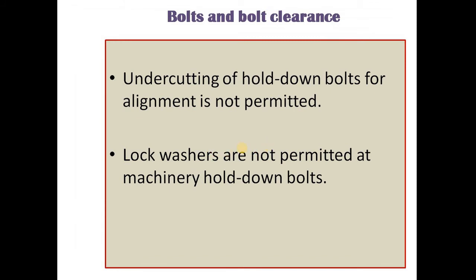Bolt clearances and holding down bolts: there should not be any undercut. I have told you, if it touches the base frame hole, then there may be tension. But you have to choose a holding bolt so that there is some clearance and it is free. And we should not use any lock washer for holding down bolts.